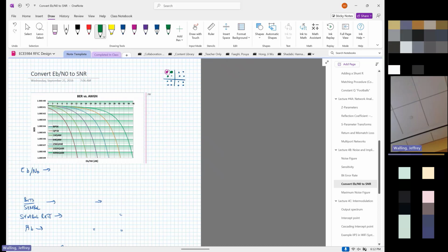You can imagine if in that same 16 QAM square that I've drawn, I go from 4 bits per symbol to 6 bits per symbol, I have something called 64 QAM. I've packed a couple more bits per symbol into the same square. All of the points are a little bit closer together, and I need better SNR to be able to detect any given one of those points. So this waterfall curve tells us how to figure this out.